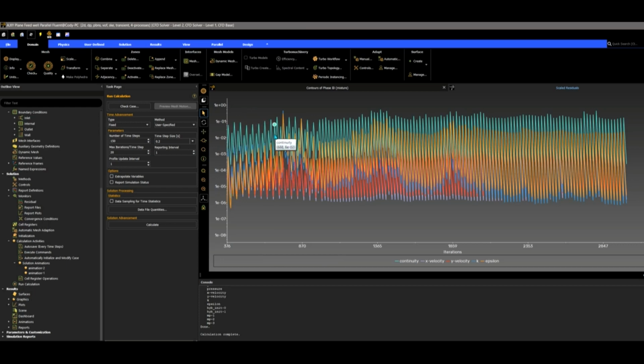Ideally, we'd have these a little bit lower by using more iterations. As you can see, they are starting to converge, and I have done a convergence check if we do use higher iterations. But for the sake of these simulations, this will be sufficiently accurate, and we are conserving computational power, even though this takes nearly an hour to complete in total.